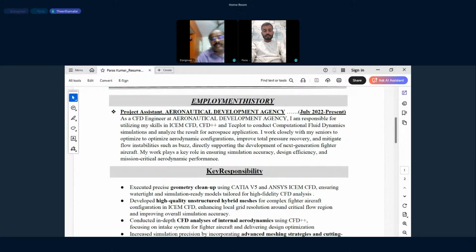Okay, and if it is canard control? Sir, canard is also there. How will the canard deflect if they want to give a pitch up? The canard has to be pitched down, I think. About the CG, the elevator is behind and the canard is in the front, so it will be the opposite direction. It has to give the same moment, so the force will be in the opposite direction. The moment will be the same.